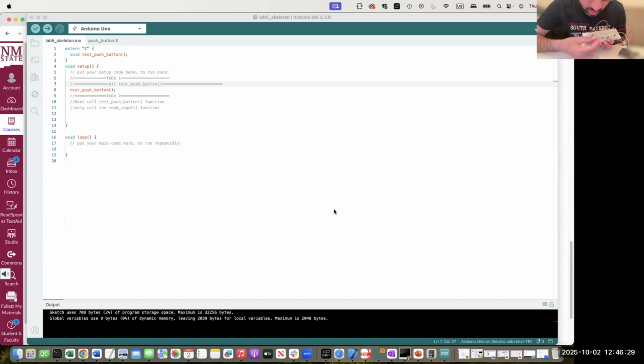So this one is Y, exactly opposite to the W. Let's say that I insert my jumper cable in the hole where Y is connected, right? If I do that here, you can see that all the LEDs are switched on, which means that W and Y are connected together. So I should not connect pin 9 of the Arduino board with the leg Y of the push button, but I should make a connection with the other one, which is basically Z, right?